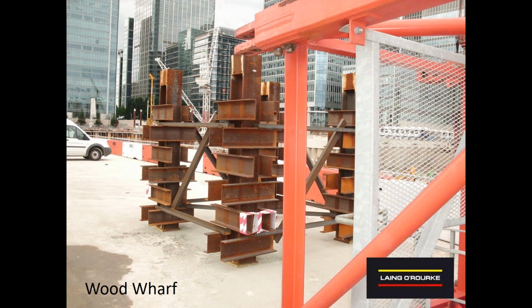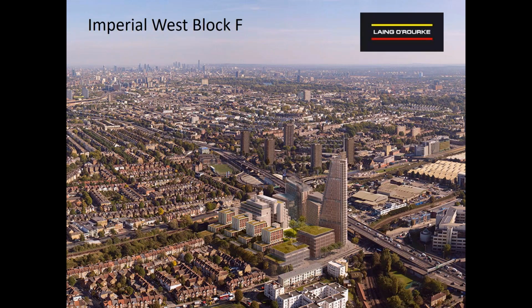But in terms of loads on the base, the vertical loads will start to creep up slightly, probably, if you go from 50 meters to, say, 100 meters with some ties. But the moment on the base, if anything, might reduce. So the bases for high-rise cranes tend to be very similar to the bases for low-rise cranes. That is a recent Langerock project, student accommodation about 40 stories high, again in West London, a bit further out from Paddington.